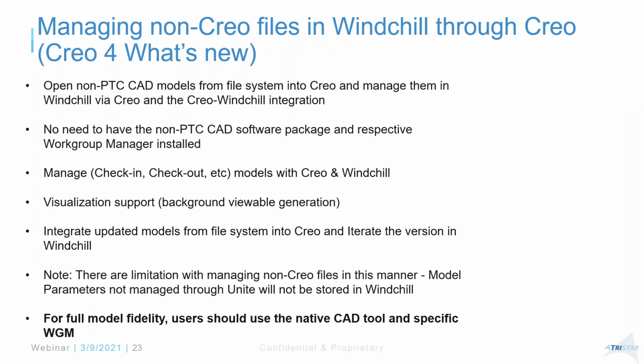And speaking about Windchill itself, like I said, Unite technology is supported both with Windchill as well as without Windchill, right? You're able to support both. It creates a wrapper file, and they're managed in both cases. But starting in Creo 4, PTC did make an update where, without the need to have a workgroup manager, you're able to manage, check in, and check out those non-Creo files through the Creo workspace, right?